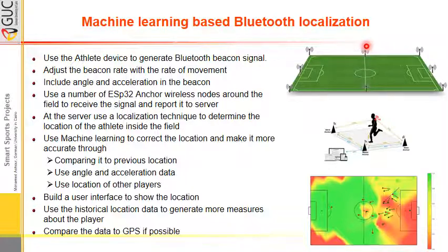They will do a very simple task of only receiving Bluetooth beacons and sending it using Wi-Fi to a server. So how the project will work: each player will wear a device. This device will regularly transmit what is called a Bluetooth beacon. This beacon is a regular signal that contains the MAC address of the device of the player. This signal would be received by all these anchor points, and a technique would be used to find the location of the player in the field.